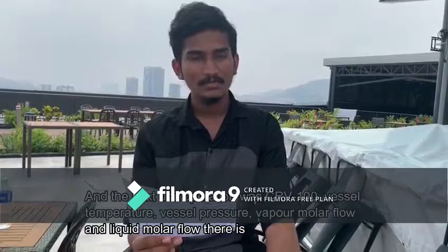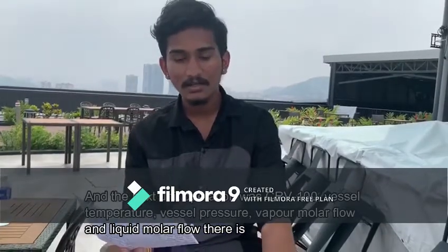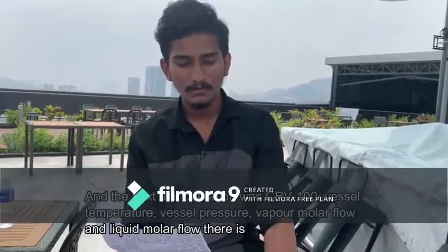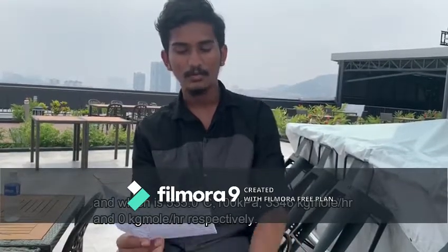And the next unit operation was CRB 100, with vessel temperature, vessel pressure, vapor molar flow and liquid molar flow of 535 degrees Celsius, 100 kPa, 3346 kilogram mole per hour and 0 kilogram mole per hour respectively.